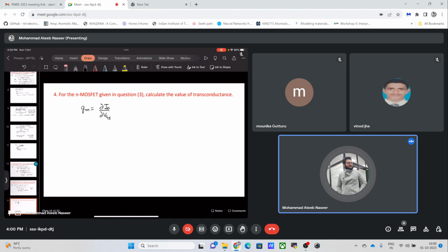So in this case, for example, with silicon, we will have this effective mass dependency for Gm as well. You must have heard that strained silicon channels were used in order to enhance the mobility. The mobility enhancement can be attributed to the change in the effective mass as well, because strained silicon has a different band structure compared to pristine silicon.